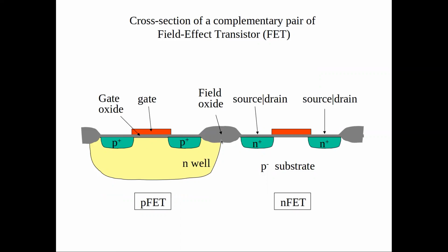And it's usually just everything that is around transistors that is separating the semiconductor from whatever is on top. If it's a transistor channel, it's called the gate oxide. It's exactly the same, SiO2. It's the same material. And if it's not under the masks that are controlling the thickness, it's allowed to grow. In fact, it oxidizes just with oxygen. It gets bigger, and then it's thicker. That's why it's drawn like that.